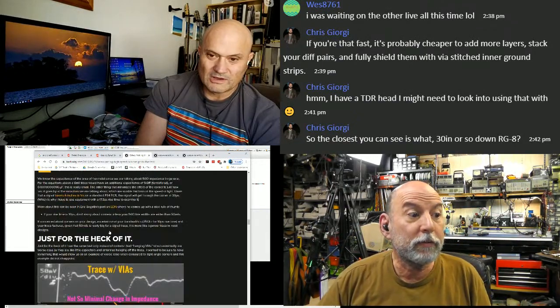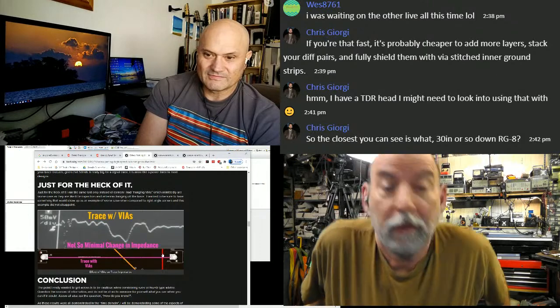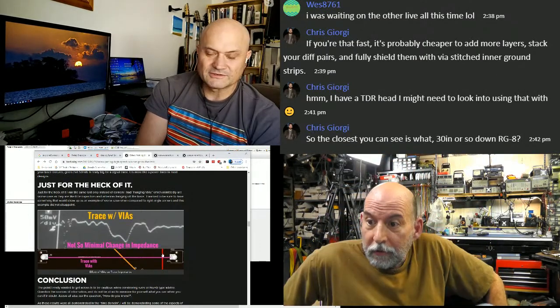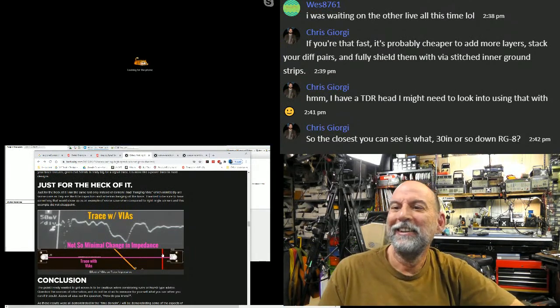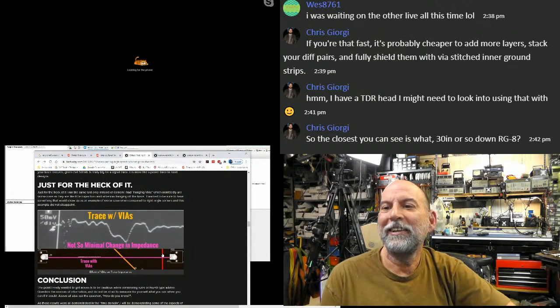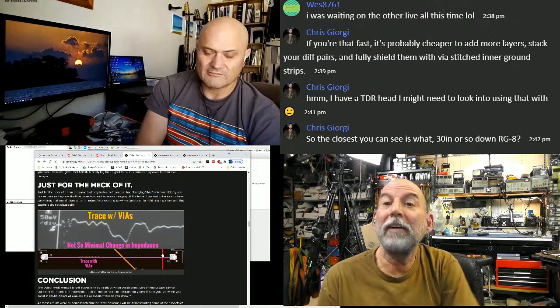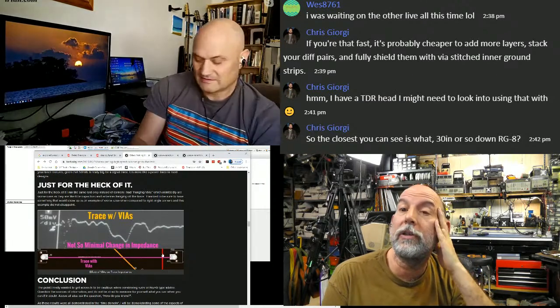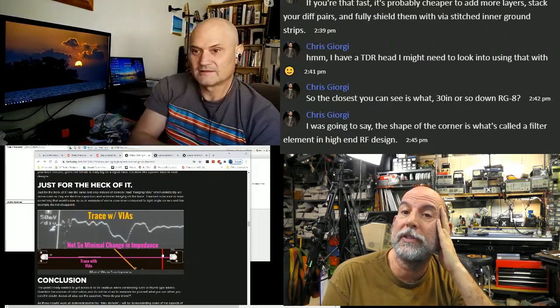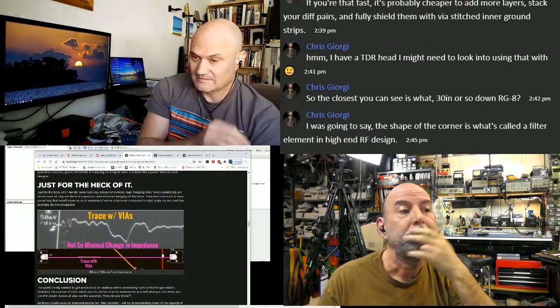Well, and beyond that, what matters more is vias. Yeah, beyond that, no CAD tool actually makes square corners like that anyway. They're all based on routing the board with a round shape. Oh, aperture. Good point. That's the days of, we used to do laser apertures, and you would definitely see the laser radius in there.